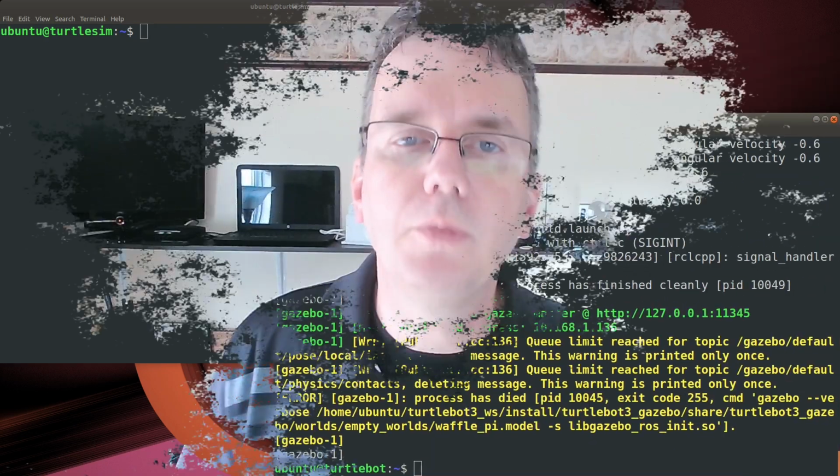A node can publish data on a topic. A node can subscribe to a topic to receive data. But how is the data itself formatted? It's formatted as a message. ROS message structures define how data is exchanged between nodes on topics. There are a few different built-in message types: strings, numbers, booleans, the kind that you'd expect. And it's also possible to combine these into more complex message structures.